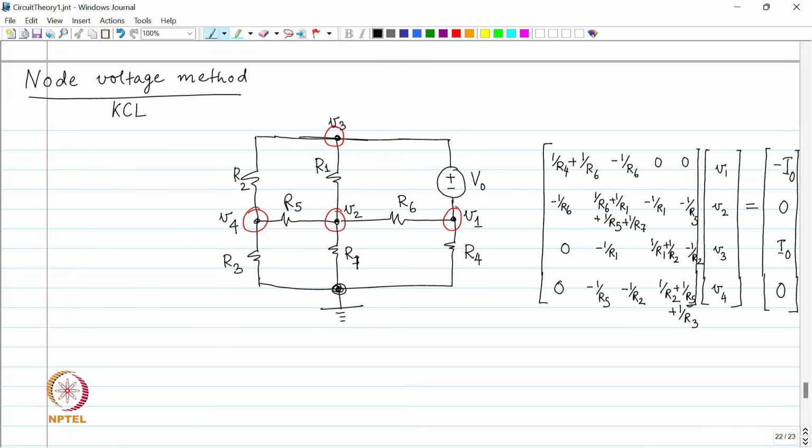So, if I go to V1 and try to do a KCL, I just will not be able to do that KCL. Do you see that I can't do a KCL? Why can't I do a KCL? Because in the branch with the voltage source, the current is not known. Okay. So, I can't do a KCL at V1. So, I am stuck. What about V3?